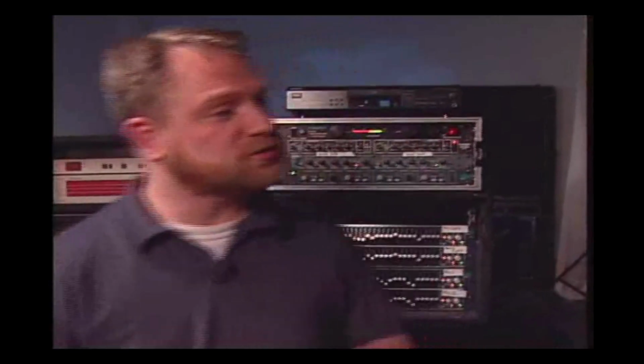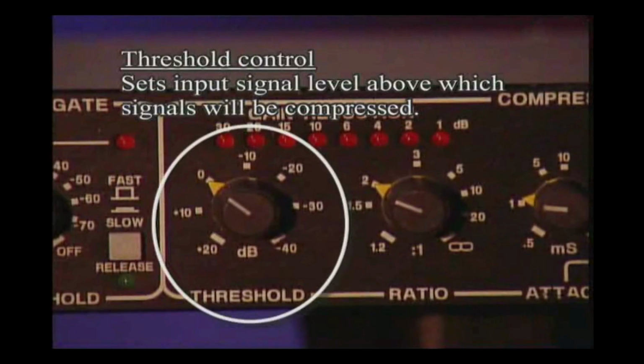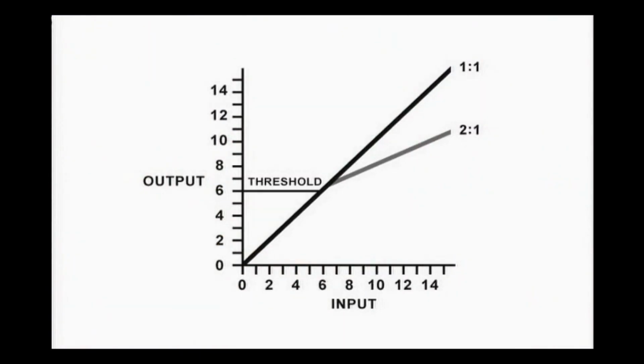Can you show us how it works? It's fairly simple. There's 4 controls. The threshold control allows you to set an input signal level above which signals will be compressed. The higher you raise this setting, the higher the level of the input signal before the compressor kicks in. The ratio control sets the compression slope. The slope determines how the output signal will change in relation to the input signal once the input signal exceeds the threshold. The slope is stated as a ratio, such as 2 to 1.